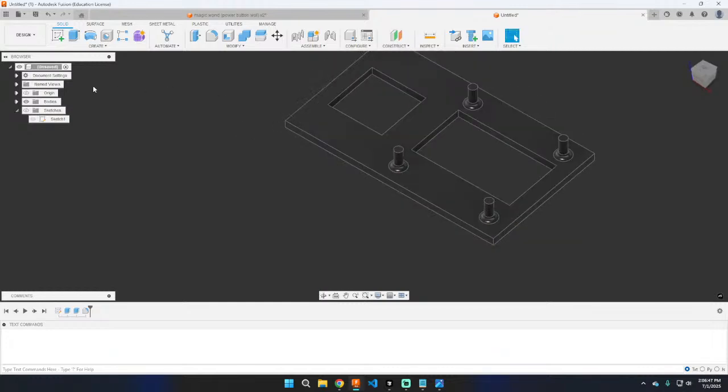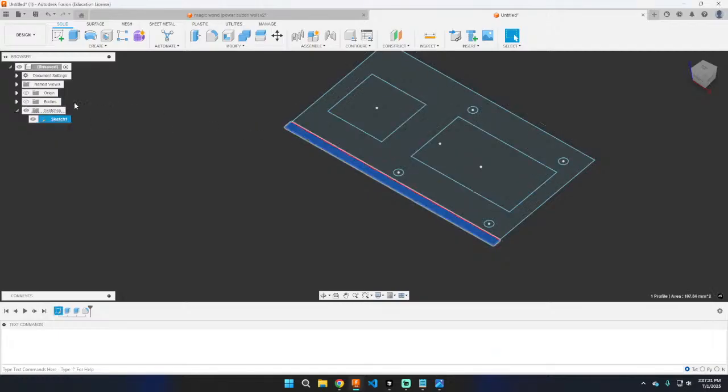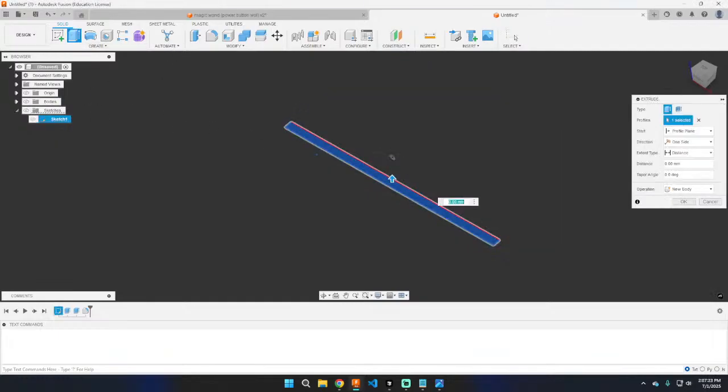Let's extrude. I'm trying to think how wide I should make this, because it's not going to be very skinny. Sorry, I'm not fat shaming. Maybe just a little bit. But the width of our module is about 25 millimeters. So I'm also going to have to give it some wiggle room. So I might extrude out about 30 millimeters. Yeah, so take this here, extrude out about 30.